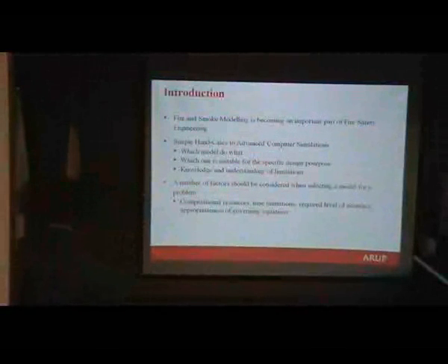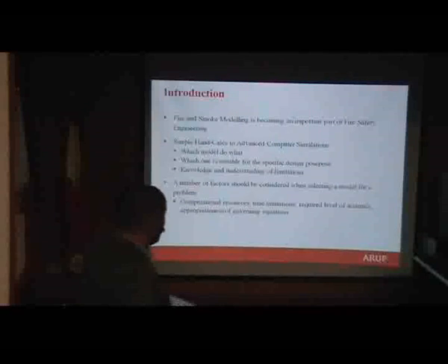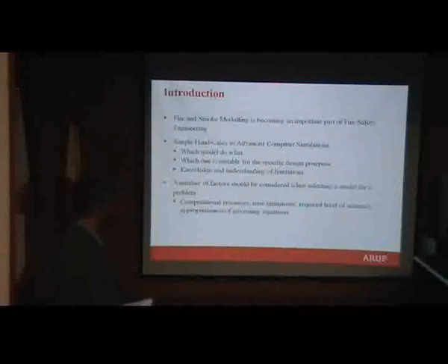So fire smoke modeling is becoming an important part of fire safety engineering. And this can vary from hand calculation to advanced computer simulation. What is really important to understand is which model does what, and which one is suitable for the specific design purpose. It's also really important to have knowledge and understanding of the limitations of each model. And also, as we are in industry, it's really important to understand, for example, the computational resources you have available, the time limitation, the required level of accuracy, and so on.